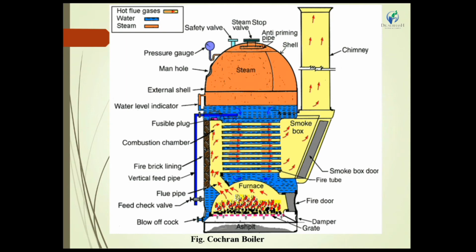First we have to start from the bottom side of the boiler. At first we have to apply coal from the fire door, or initially primary air and coal we have to draw into the fire door. The grate provides the initial platform to ignite the coal. After the ignition starts, we have to input coal and primary air step by step from the fire door. This coal is ignited and produces heat and ash.